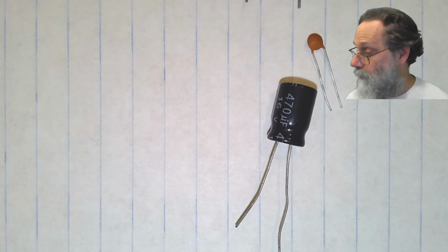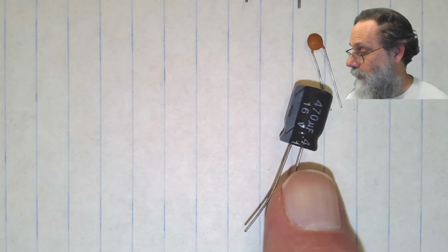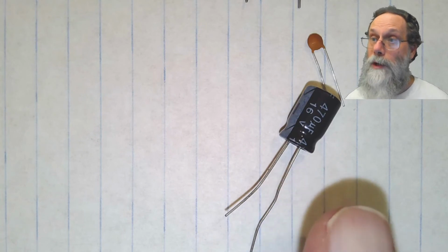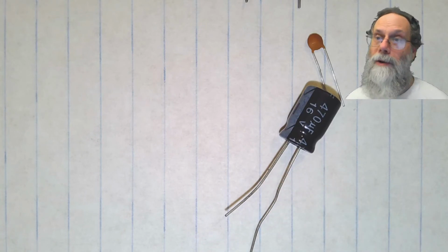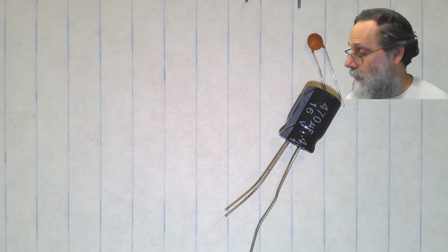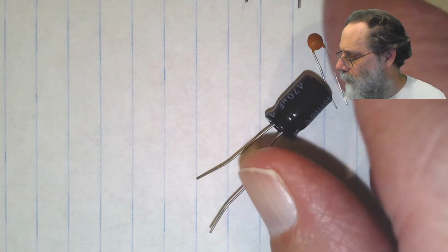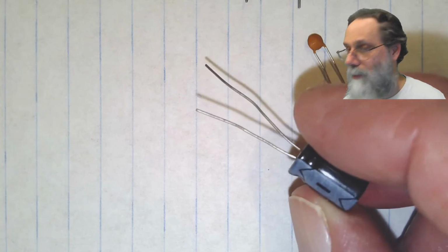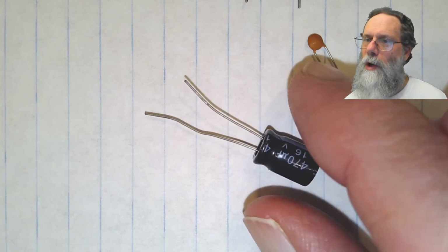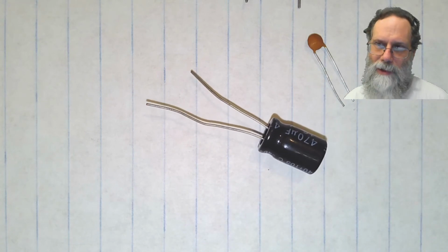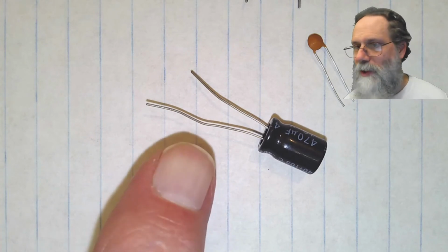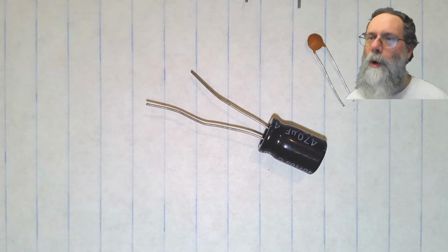And that allows here, this one, which is a fairly cheap one, is 470 microfarads. So 47 times that 10 microfarad capacitor in the ceramics. But you notice there's a weird marking here on one of these wires, the minus sign. That's because this is what's called a polarized capacitor. You can only put positive charge on one side, negative charge on the other.